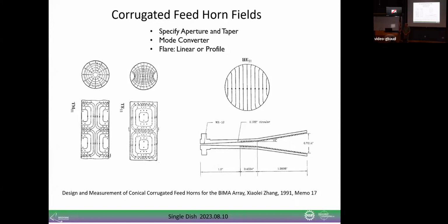One more online. Also, how are certain TE and TM modes isolated? Presumably all mode frequencies above a threshold would appear in the signal. Yeah, so that's really the feed properties. They're really hybrid modes. If you think of the signal coming back the other way, you have the hybrid mode here with these two modes. Going in the opposite direction, this mode converter converts it back to TE11 mode, the lowest order mode of the waveguide.